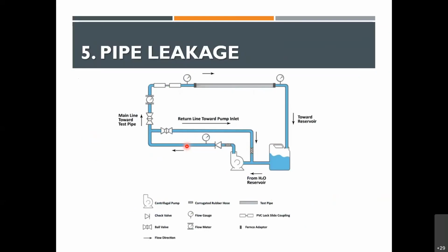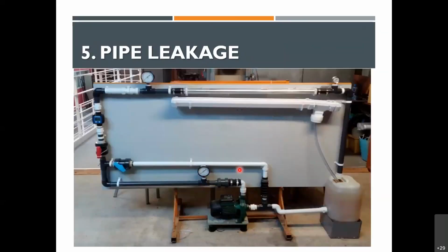And here we worked by creating a benchmark pipe rig as well. For the benchmark pipe rig, we controlled the flow, we controlled the damage on the pipe, and we also controlled the leakage on the pipe, and that's the pipe section. So that's how it looks. This is the pipe section. You can have damage and leakage on this. You can see that the gauges are here controlling everything. There's also a pump, and we control the flow rate as well.